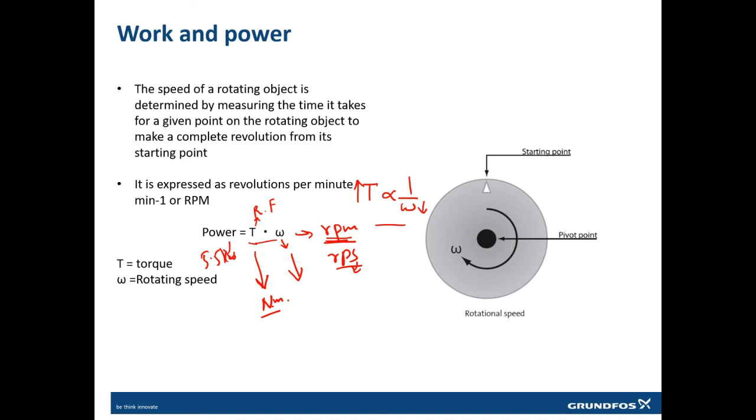That is the reason, if you are going uphill in your car, you will slow down your car, or your car will automatically slow down, or you will put your car in a lower gear. And if you are going down the hill, you will not put it in a lower gear, you will increase the gear, because you don't need too much power. So the motor output is the force which it is providing at some speed.